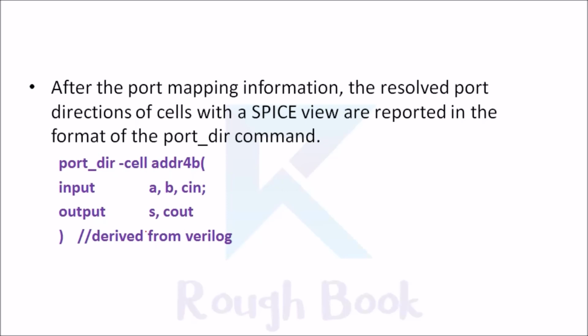After the port mapping information, the resolved port direction of the cells with SPICE views are reported in the format of the port_direction command. This is the command reported after the port mapping information. So this is about the port.rpt file.